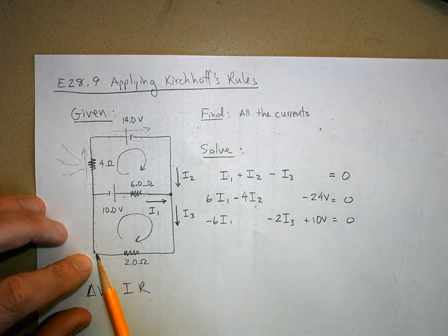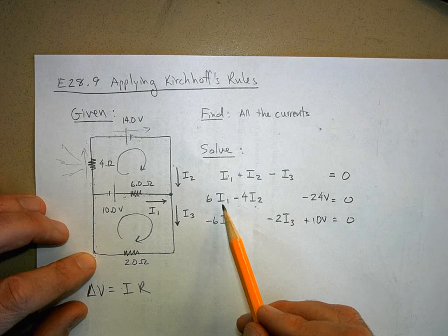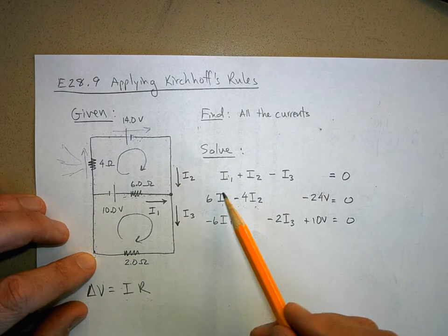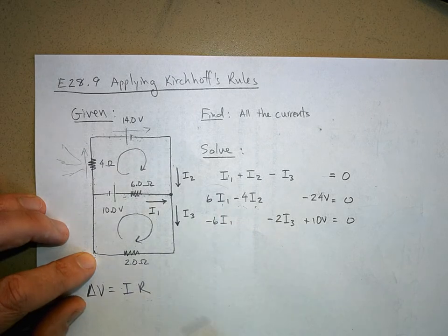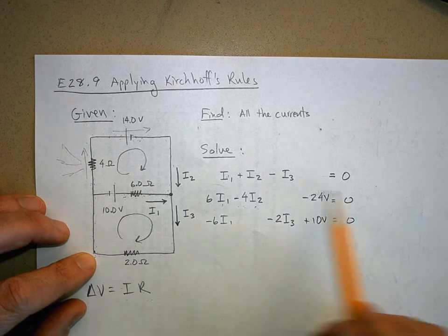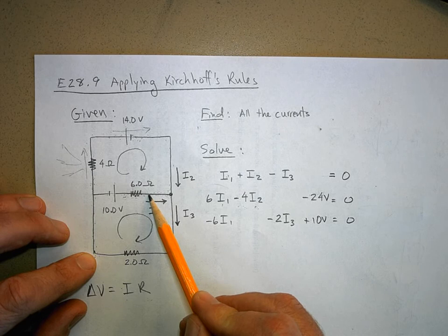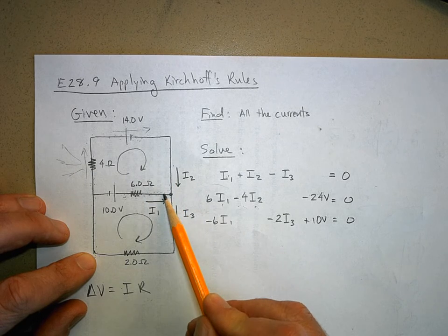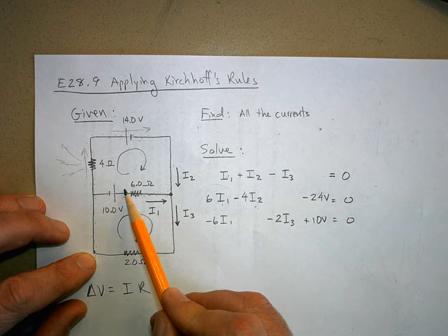Okay, let's do it again. On the previous equation, you have plus 6I1, and that's because what? Well, the question is, why is this positive 6I1 and this negative 6I1? Look at the direction voltage man was walking. In this top loop, which is what we used to create this equation, when we got here, we went against the current. So we were here, and then we took a turn. And then we're swimming against I1, and we have to jump up this little waterfall of a resistor.